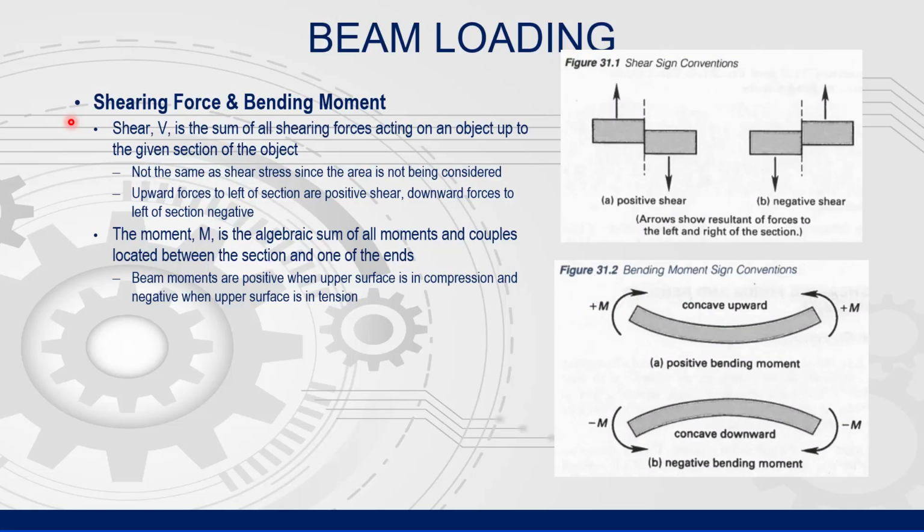Shear force, represented by the variable V, is the sum of all shearing forces acting on a beam from the left-hand side up to a given point of interest. This is not the same as shear stress, since the area of the beam is not being considered.